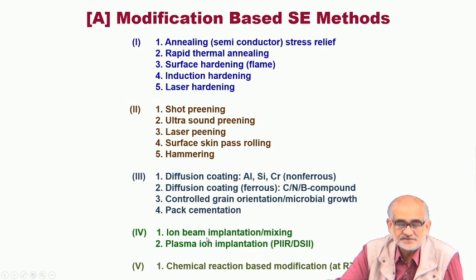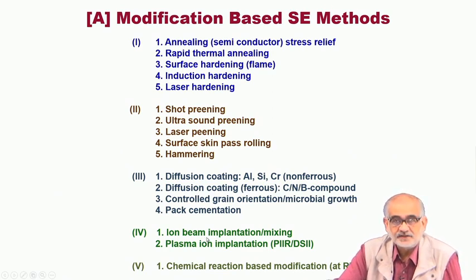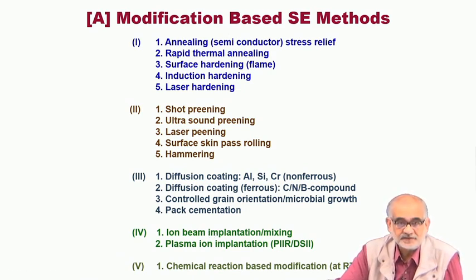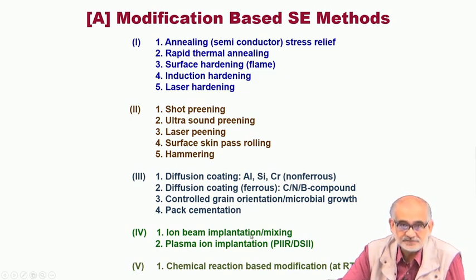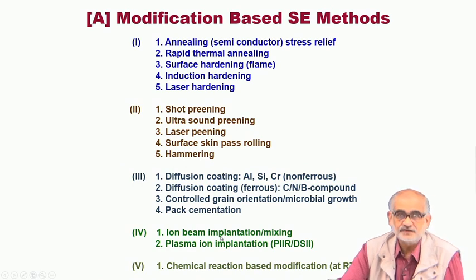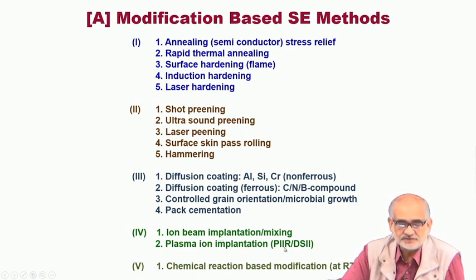And what happens in the process is somewhat similar to the cascading effect we see on a carom board or a billiard board. When one object hits one of the frontal coins, then in turn that coin hits another and so on. So you see a chain reaction, or a cascading reaction. And in the process, the ions which are implanted onto the surface reach up to a certain depth below the surface, and over a period of time, the overall composition of the near surface region, which could be just a few atomic layers from the surface, gets modified.